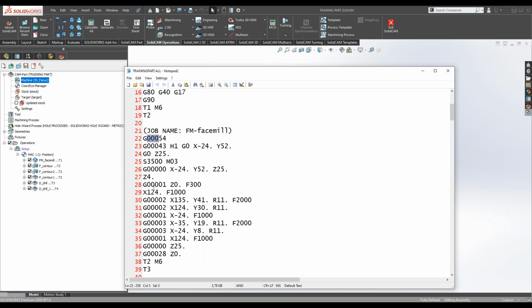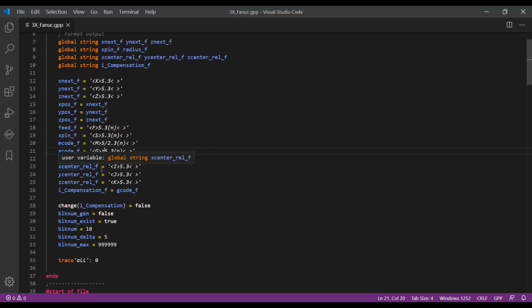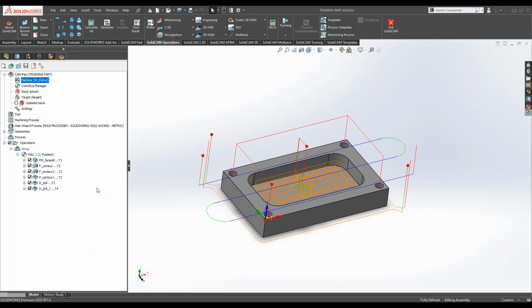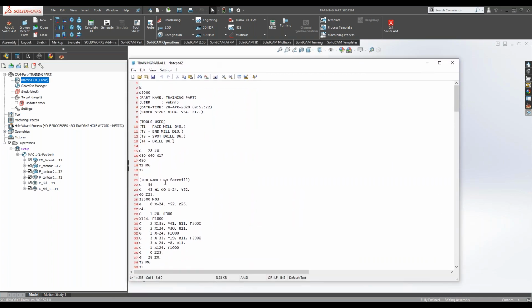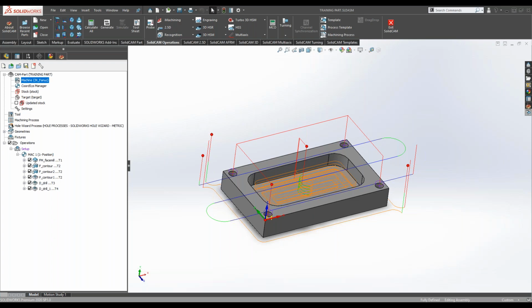Now, if we want to use leading spaces, let's delete the Z and just use an empty space. Okay, let's save this. Go back to SolidCam. Let's generate the G-code now. And what did we get? Whoa, a lot of spaces. How many? Well, how many the zeros would be? 1, 2, and 3. So this is the use. Again, some machines require a certain number of digits, and this is one way to use it. So let's close this. Let's go back to the presentation.